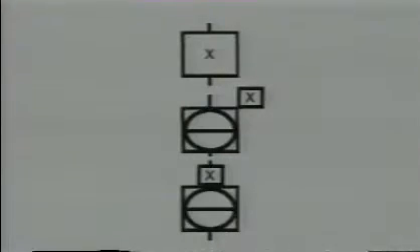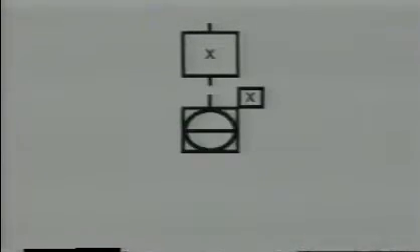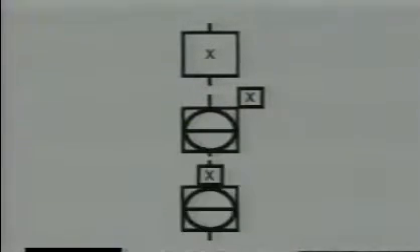Function blocks designate the computations and conversions within a loop or instrument. You'll see function blocks used in several ways. As a standalone symbol that represents only the functional aspects of a loop. As a flag designating a function of a specific component. Or on a signal line adjacent to a shared controller.